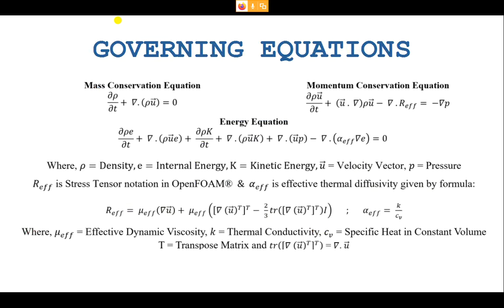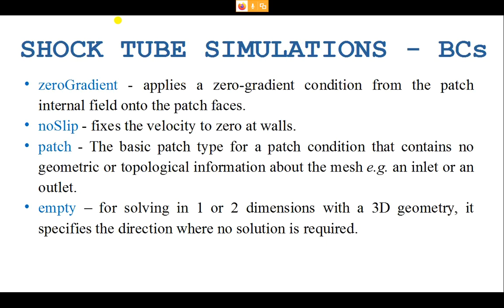So in this we have governing equations, which are the mass conservation equations, momentum conservation equations, and energy equations. This is suitable for compressible flow, and we used OpenFOAM for the simulations, which is an open source tool. The algorithm we used is the PIMPLE algorithm, and there is a dedicated solver for compressible flows. With these equations available as a solver in OpenFOAM, we invoked that solver with some boundary conditions. Like you have the pipe, you have to supply it with the boundary conditions.